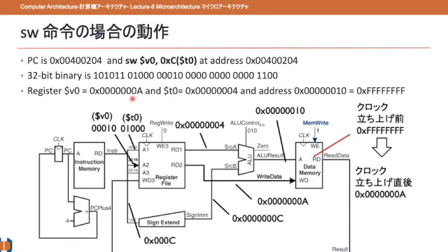Well, one more thing you must know, to calculate the memory address that comes from these two values, the offset is C here, and you must know the value contained in T0, which should be considered as a base of the memory address, right? So I also give you that value, the T0 is this.